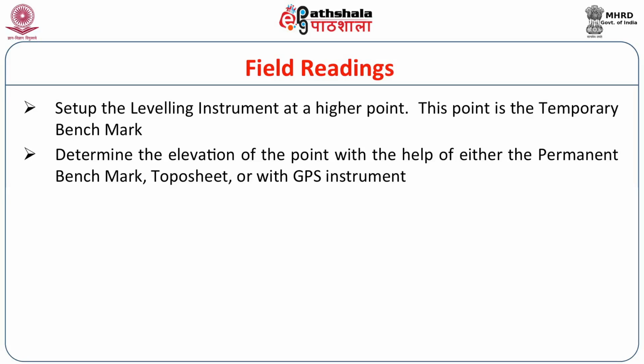So, if some benchmark is nearer to the survey area, then we can use that benchmark and then we can project that benchmark onto the point that is required for survey. Or otherwise another method is to use the GPS, a very sensitive GPS instrument, to determine the MSL at that point.